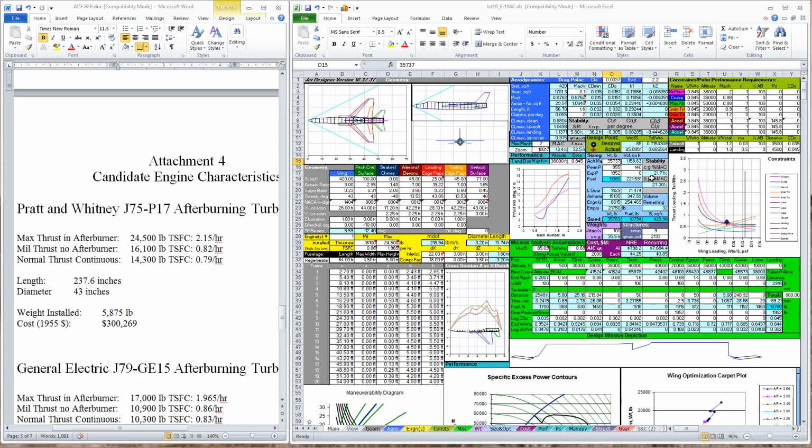Let's try 35,437. Yeah, great. So that camber helped us just a little bit. You don't want to go overboard on camber because in a supersonic airplane, camber penalizes you at the high Mach numbers. But 1% camber, that's what the F-16 and F-15 use in their baseline airfoil, so that should be okay. Now I think we're ready to go optimize.